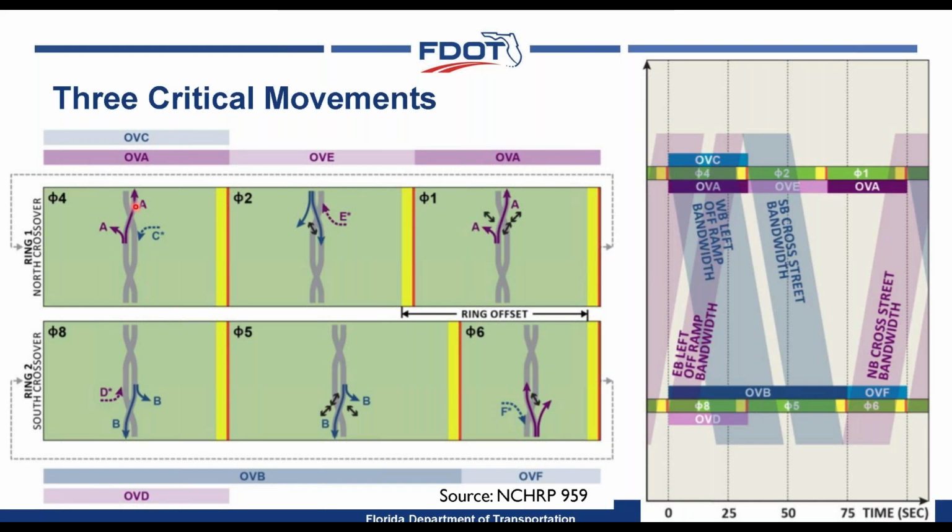So it really is more of a long northbound through phase, followed by phase 2, which is the southbound through. In the southern intersection, you end up with the same thing. Phases 8 and 5 are both southbound through as the primary movement, followed by the northbound through in the second phase. So again, it's essentially a two-phase signal as well, but now we're trying to coordinate movements with the goal of not storing vehicles in between the crossovers if possible.